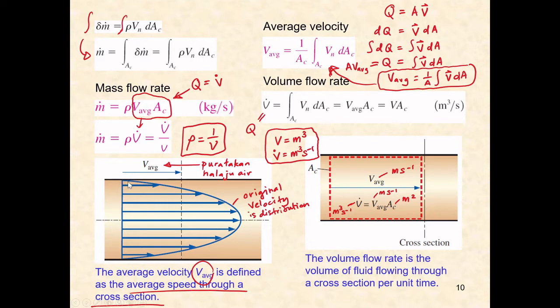That's why you get almost zero flow near the wall and near maximum in the middle of the pipe. That's happening in the pipe flow system. It's the same for liquid and maybe, to a lesser extent, for gas flow. Generally speaking, you could assume this kind of profile develops. So that's why this is called the velocity distribution in the piping system.